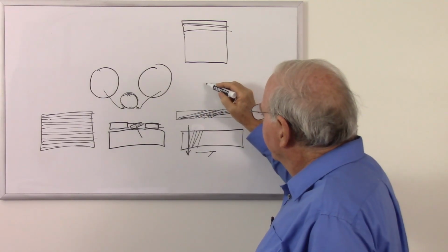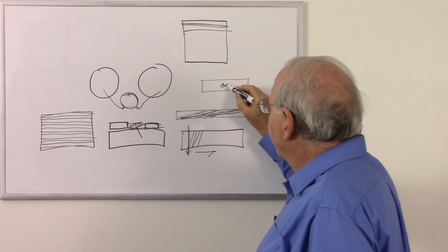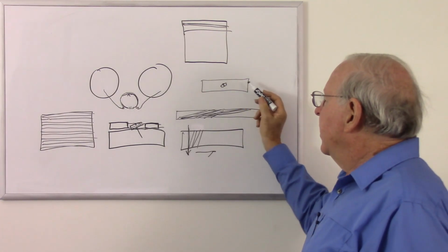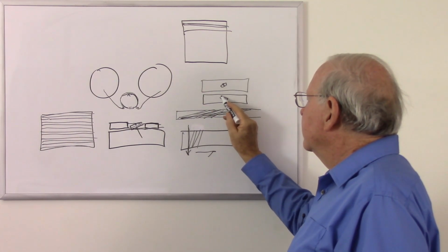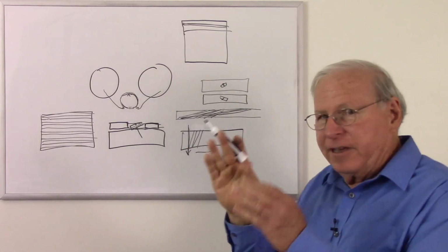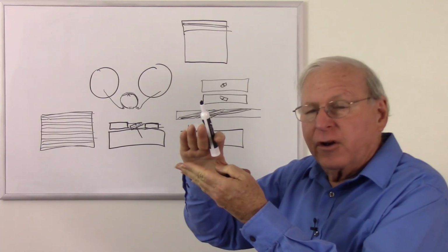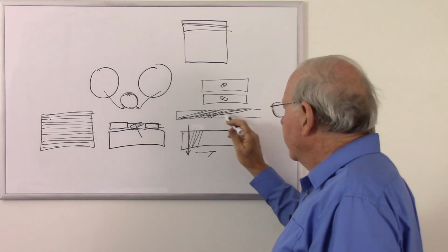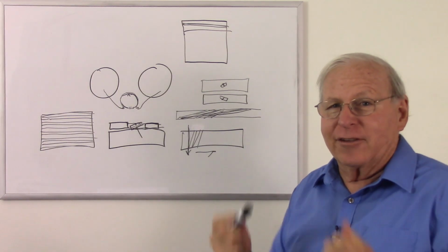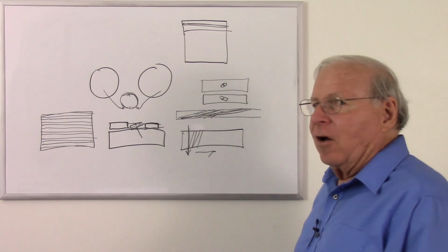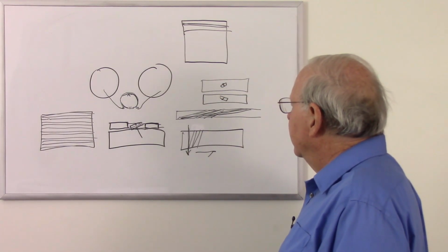So the heads, if we look at the drum, head number one is skewed that way. So the gap is canted, but it spins around the other side and we see the other head and it's skewed the opposite direction. So because these magnetic fields were laid down cross to each other, they wouldn't interfere with each other, so there could be significant overlap of the tracks as they were laid down on the tape. And so if you look at an old VHS system, you might see something that says double azimuth. Cool. Yeah, all VHS were double azimuth. That's the angling of the head to lay that down on the tape.